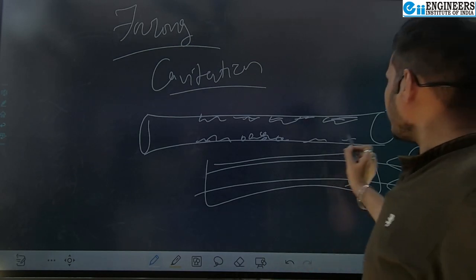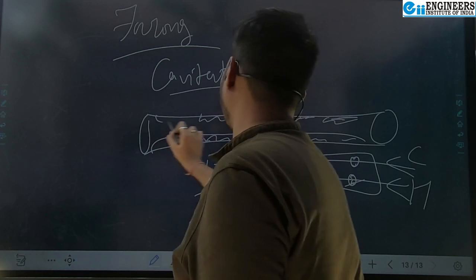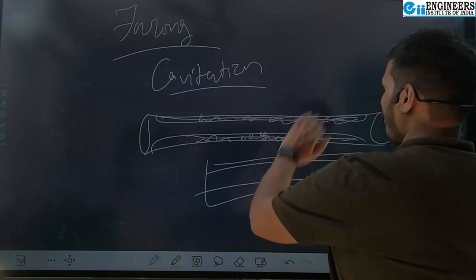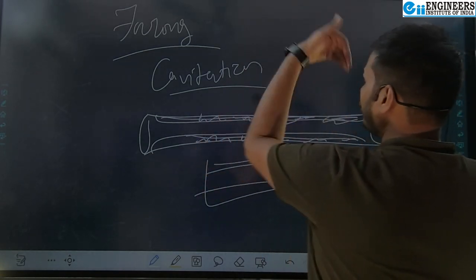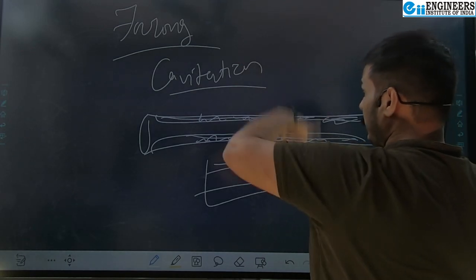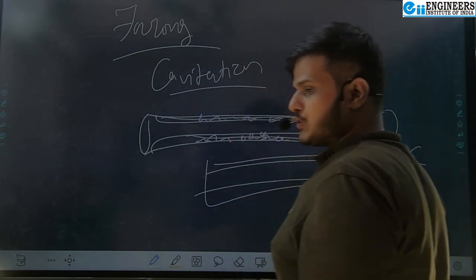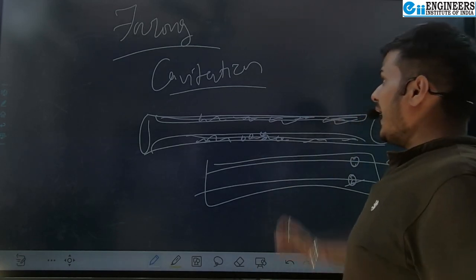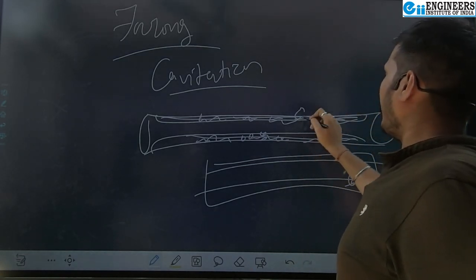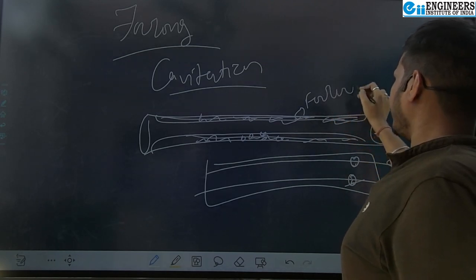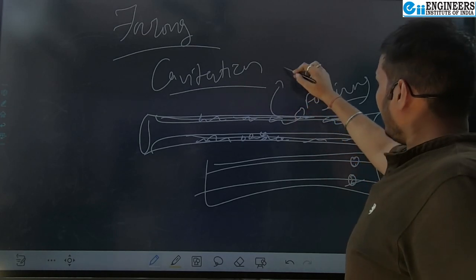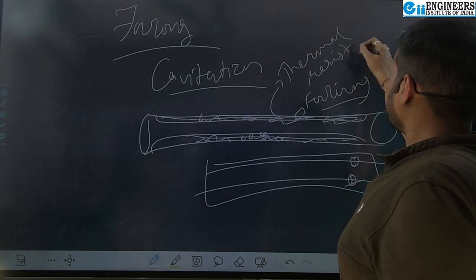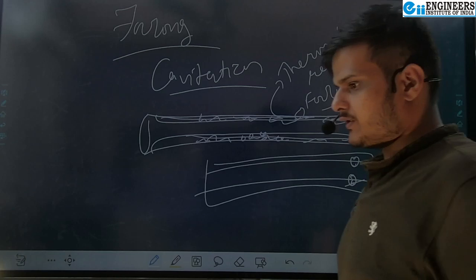So this forms a scale-like structure or a layer of dirt that offers resistance to the heat transfer from the surface of the heat exchanger, so the heat actually transferred during the process becomes lesser in magnitude. This is known as the fouling of the heat exchanger, and the scales offer a thermal resistance to the system in which heat transfer is taking place.